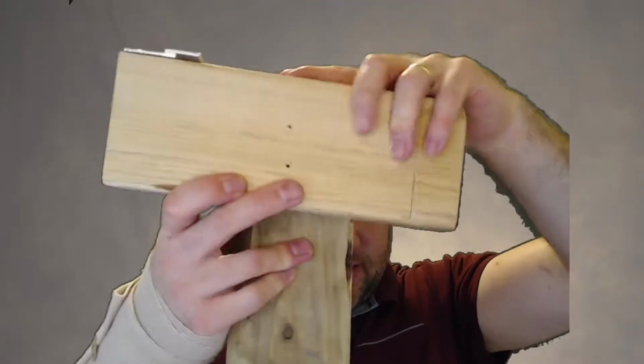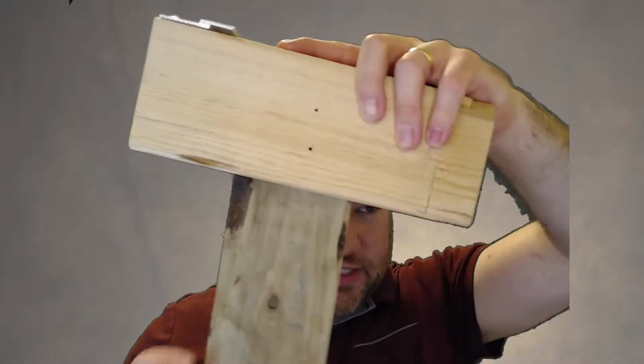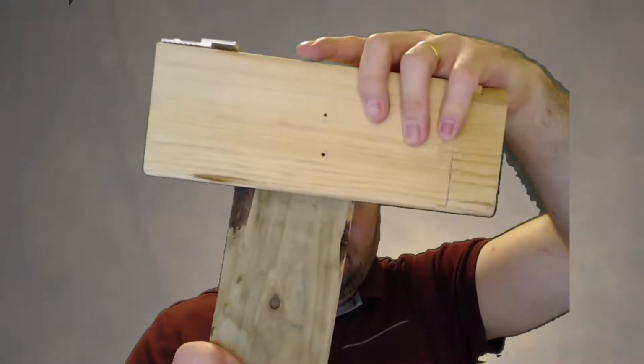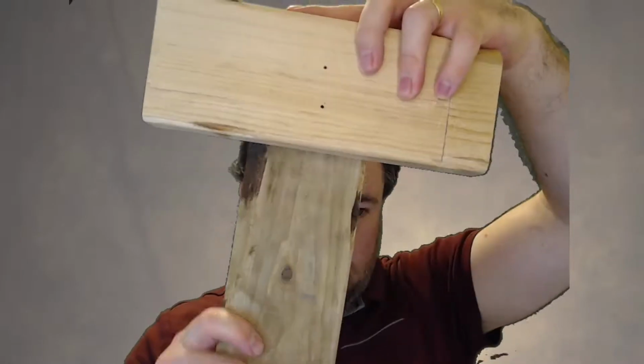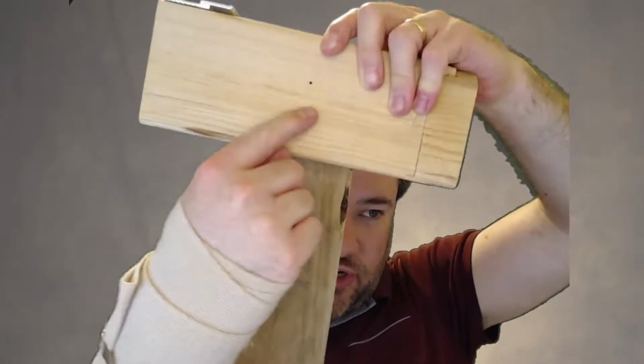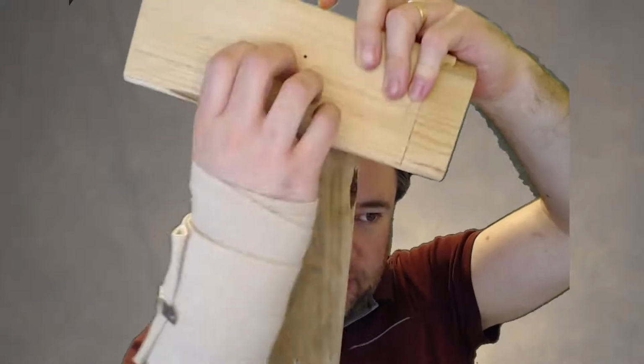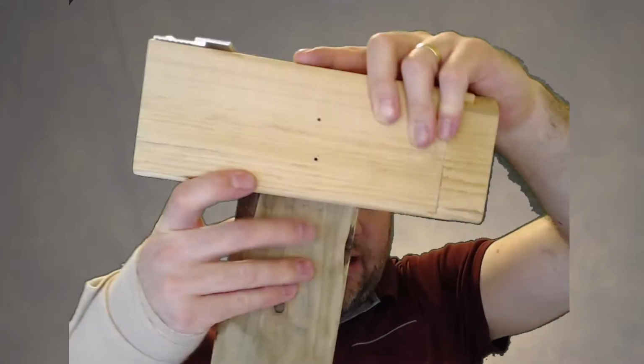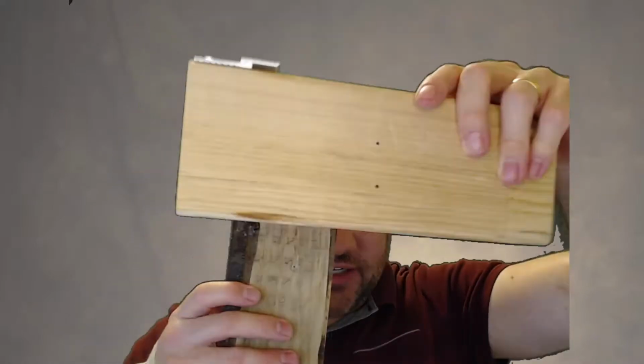Now, obviously, in this case, calculating the strength on one side of the connection is going to be very different than calculating it on the other side, right? Because for this horizontal member, when this pulls down, the bolts are going to want to pull down, and I'm going to be splitting this member apart. And so for this side of the connection, I'm going to calculate the splitting failure mode.